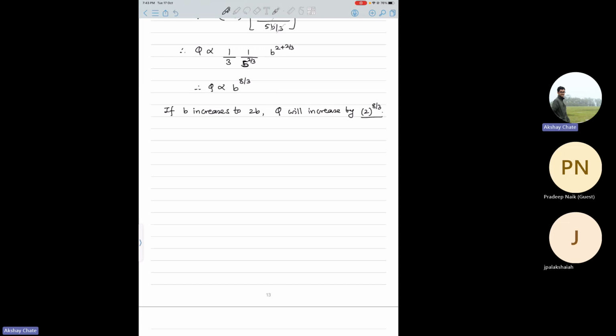Then moving on, yeah. So there is something called the efficiency for a particular flow channel. They define some efficiency, so they call it an efficient channel. So what efficient channel means is, for a given cross-sectional area, you should have maximum hydraulic radius and minimum wetted perimeter.